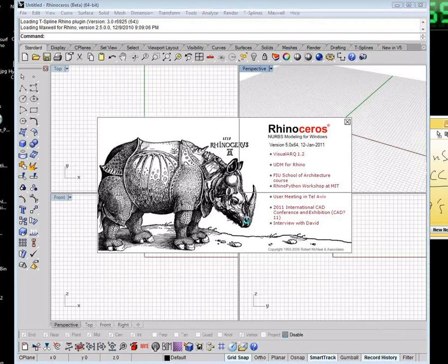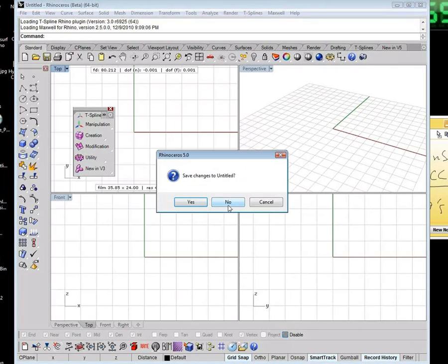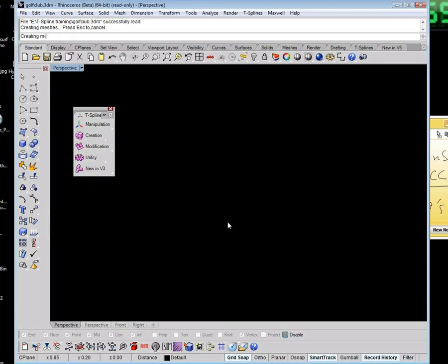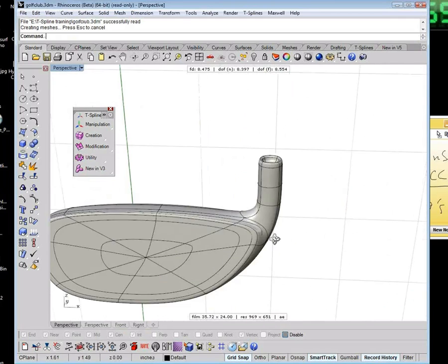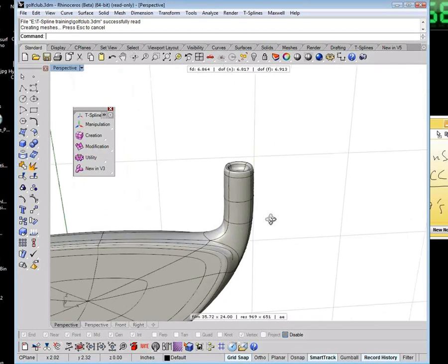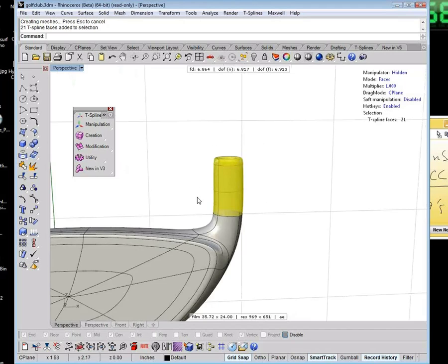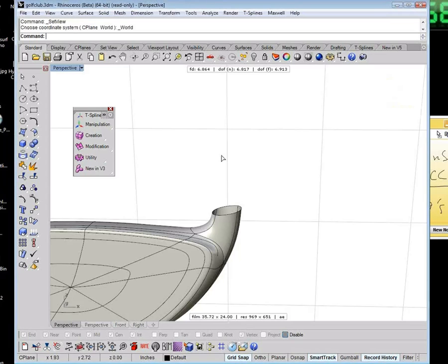There are other ways to do that by just using some Rhino commands like the blend command, or using a T-Splines command like the match command, that will keep those as two separate surfaces, and then that will have the nice effect that it won't change one of the surfaces. So depending on whether it's more important for you to have an aesthetic blend, or to maintain one part of that to be exact, you can use the different situations.